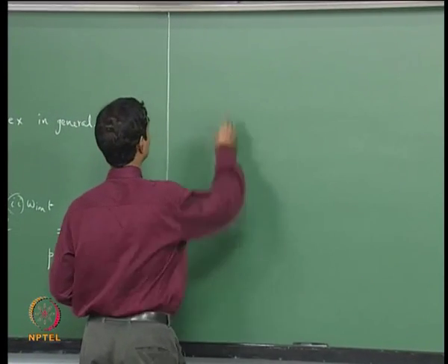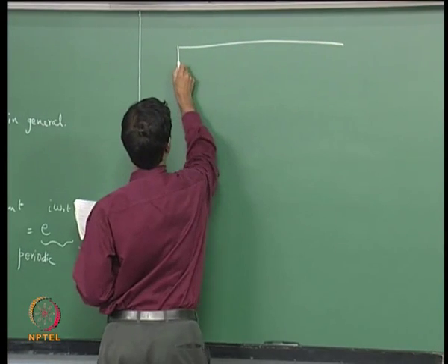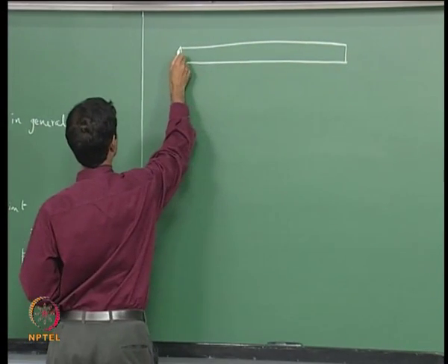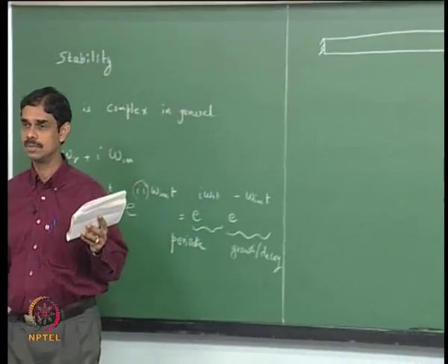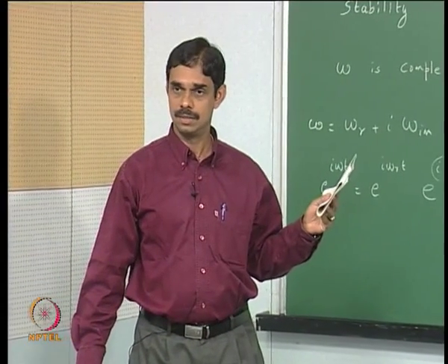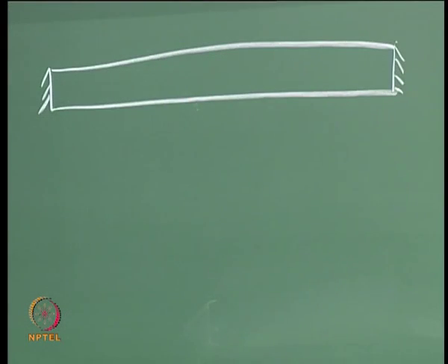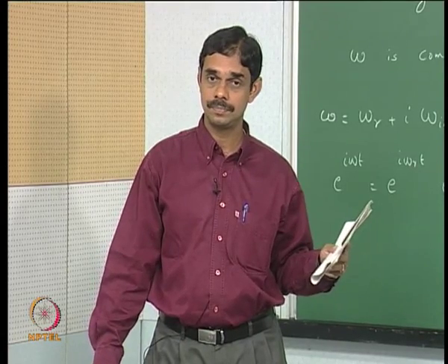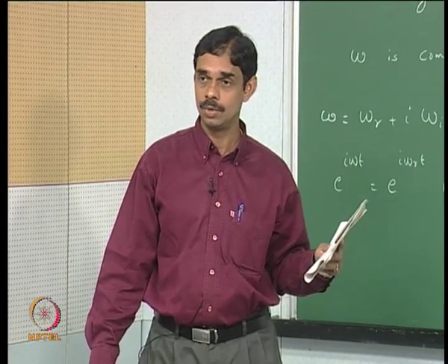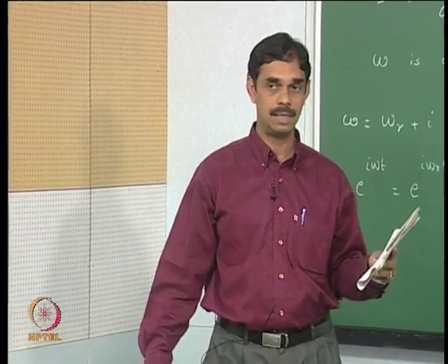We looked at a problem of a simple pipe which is closed at both ends, and did you get any growth or decay for the system? We did not. So we got real eigenvalues, right? What are the eigenvalues for this system? Yeah, n lambda by 2. So you had to fit multiples of lambda by 2 in the pipe. So the frequencies went like n c over 2L, which is a purely real number.